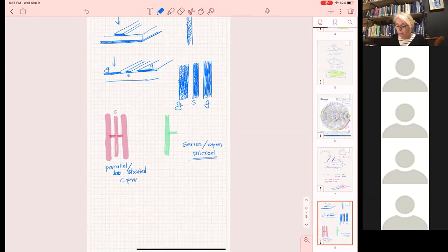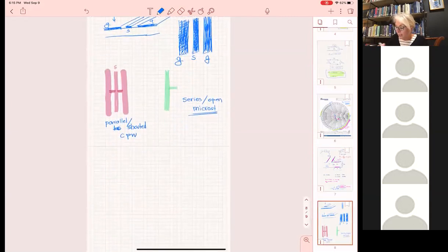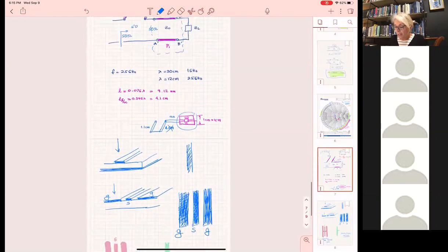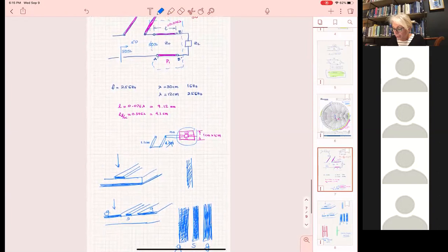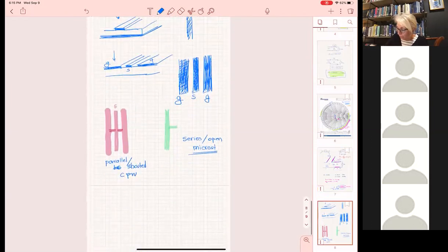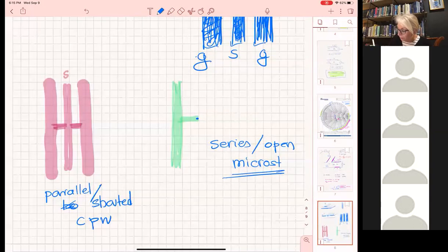So now, if we were to design our microstrip, unfortunately, to avoid the 4 centimeters, we would have to create a shorted stub in a microstrip, which means that you will have to go here, if it's that short, and open a hole. You will have an open hole, and if you do it at lower frequencies, it's okay, but it's difficult to do at high frequencies. You have to open a hole, which practically in 3 dimensions is going to look like this.